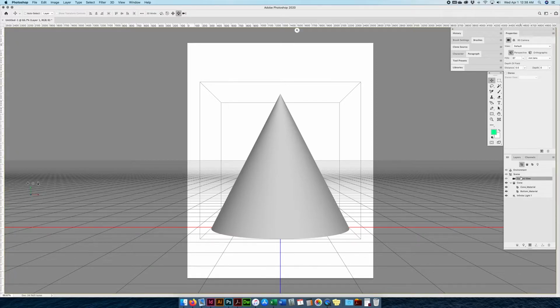One of the more important ones I want to look at is the current view. Current view, object, and light. The current view allows me to set up my camera. In my control panel I have these 5 options. I can rotate, I can roll, I can, I believe, drag or pan, I can zoom, and I can dolly, and I could zoom in and move around my camera as well. So let's play around with those initially.